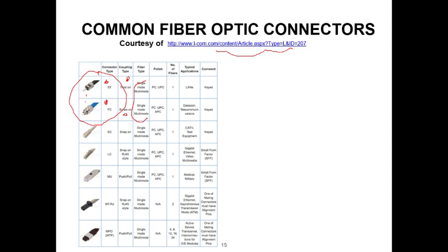They're both good for single mode or multi-mode fiber applications. For the ST, the recommended general application is for local area networks, and the FC is a little better connector, and of course costs more. Data communications, telecommunications applications. And then there's some of the other ones, LC, MU. You don't have to memorize these, but it gives you the typical applications of the different connectors.